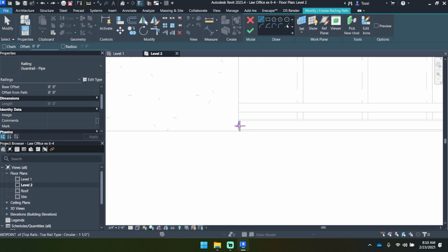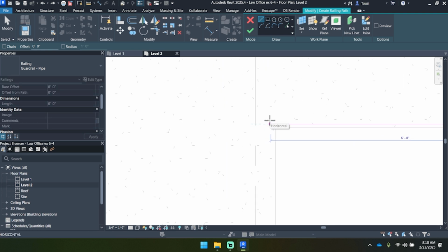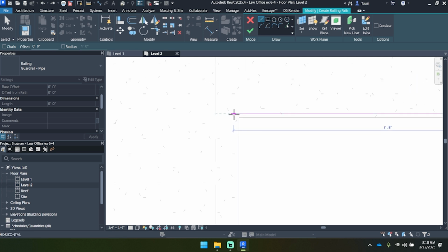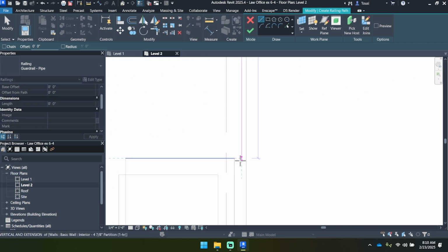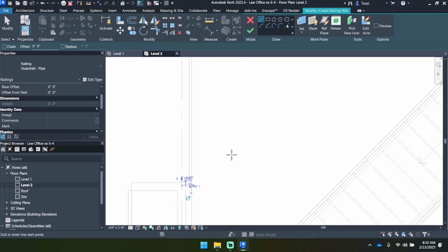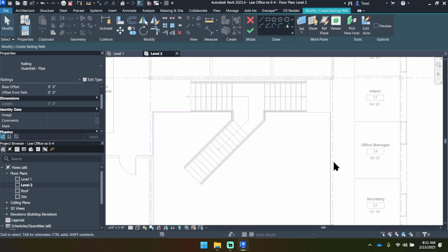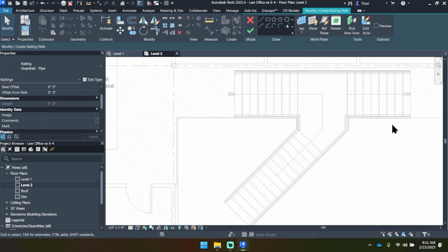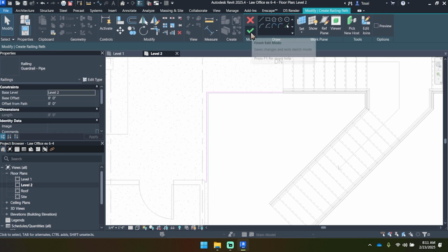So I'm going to click on the center point of the guardrail line work right here, bring it over to the edge of the stairs here, and because learning how to draw this tool is a little bit more important than us getting everything in the exact same spot, just get your handrail over here as best you can, draw it down, meeting to the center point of the wall, and then coming over from that point. Railings need to be linear and connected and uninterrupted. So, although we do need more railings over here, we cannot draw the line work for the railing as it would not connect those two pieces. So once you are done with these three, go ahead and press checkbox.